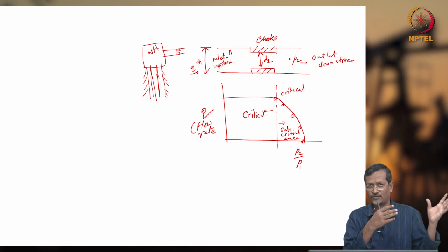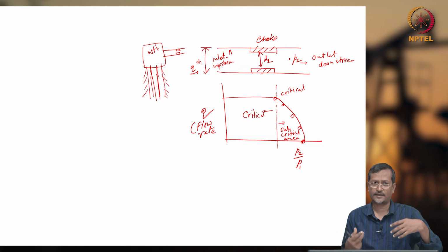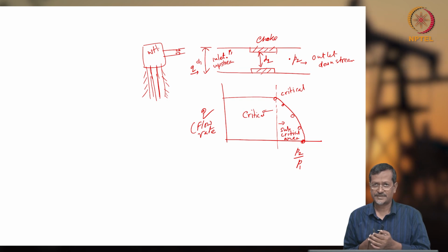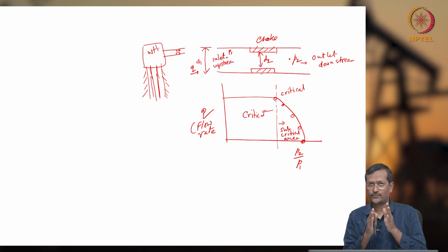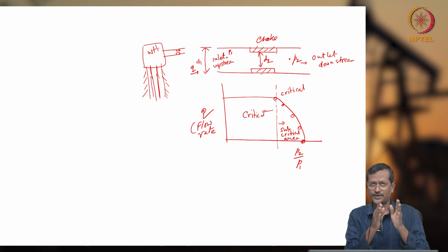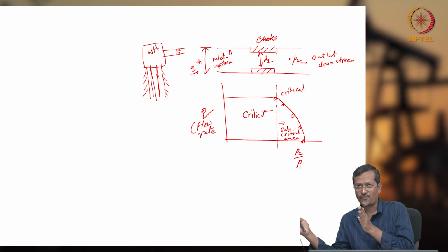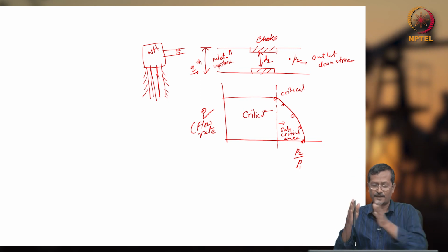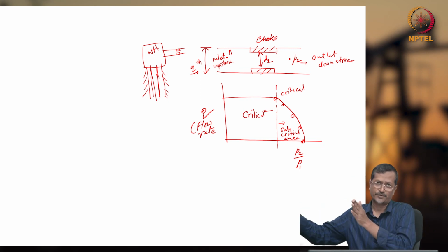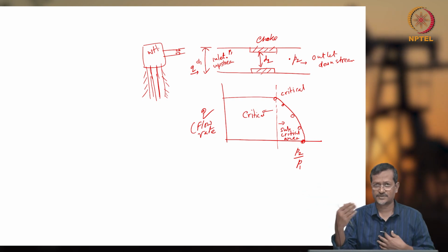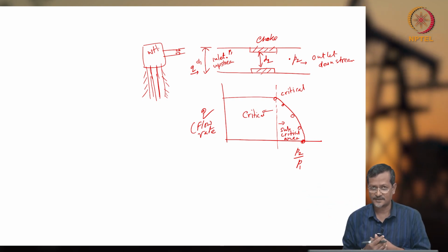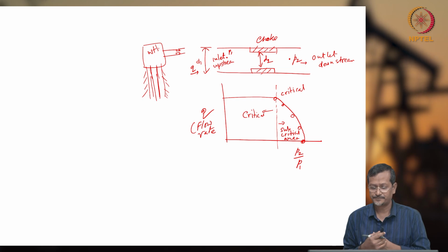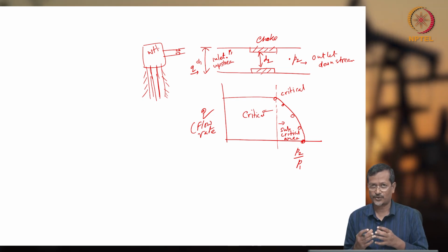So in that case, a helicopter carrying all the equipment and removing piping, tubing, then recompleting the wellbore will be a very expensive affair. So instead of changing the wellbore or the tubing pressure and flow rate, you change the downstream of choke pressure, so that your whole system will be synchronized, and after the choke you can change your pressure. That will be much easier to handle, because it is on the surface, and you don't have to bring a rig for drilling, redrilling or completing. Okay, so that's the beauty of the choke system.